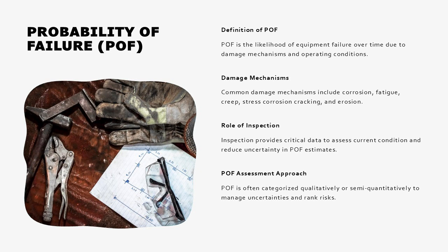Inspection plays a critical role in POF assessment by providing data on current equipment condition and reducing uncertainty about damage extent. The quality, coverage, and effectiveness of inspection methods directly influence the confidence in POF estimates. In many RBI methodologies, POF is categorized into qualitative or semi-quantitative levels rather than expressed as a precise numerical probability.